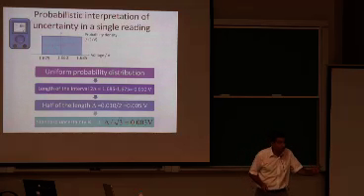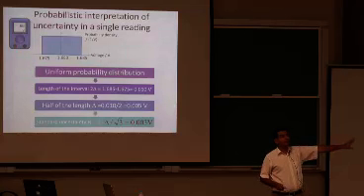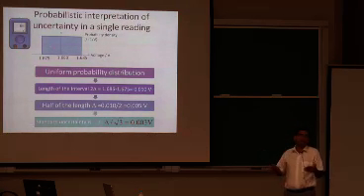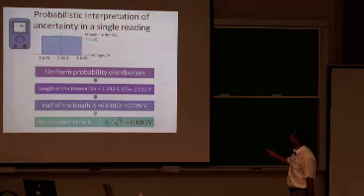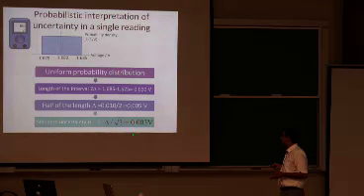So it's a uniform probability distribution function because you're using a digital scale, and you're equally ignorant of all the possibilities. All of these possibilities can occur with equal probability, in other words. So what we do is look at the length of this interval. The interval has a length of 0.010 volts. Half of this length, from the best estimate to one of the edges, is 0.005 volts. Then you divide this 0.005 by root 3, and this is your uncertainty in the reading.